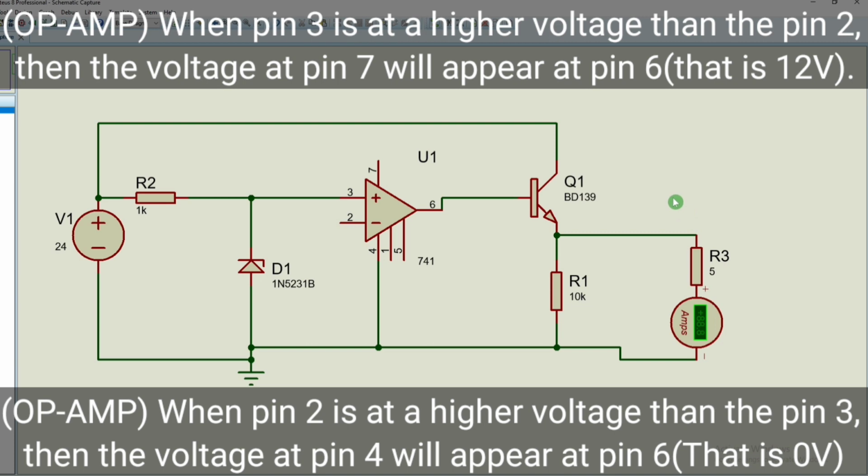And the moment it decreases from 5 to 4.9, this connection should be established again. So this BJT will act as a switch between these terminals. The moment the voltage crosses 5.1, it should be cut off, and the moment the voltage drops from 5 to 4.9, this connection should be maintained and the voltage will start increasing.